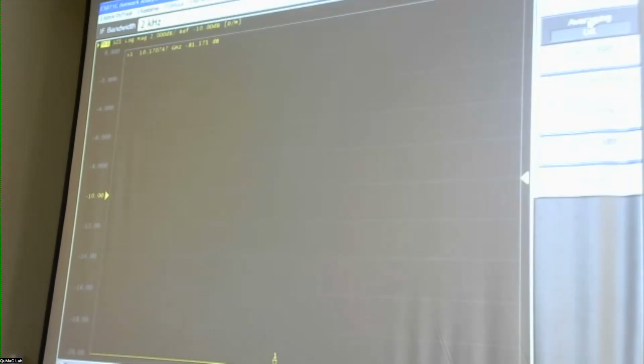Okay. Can you repeat that, how the averaging works? Suppose I am at a point taking 16 seconds for one sweep, versus taking each sweep for 1 second, 16 times, how does that work? Because the signal is coherent, it always comes back with the same phase, whereas the noise is random. So this is no different than sitting at the same point and measuring for longer. It's just you're doing it in installments. You took a little bit of data, you came back and took more data, and then you average it.